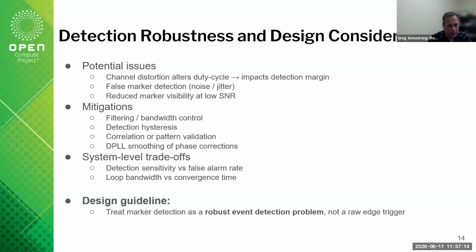So you can't have concepts like going backwards in time, which are going to be hugely devastating to something that's trying to capture events, and you have to worry about relative error time events of when those events occurred. Especially if the own system goes back in time and sends an event out that looks like it happened earlier than an event that happened within the same system just because you went backwards in time. You don't want that. So you want to be able to mitigate that cleanly through PLL smoothing techniques and do its own phase corrections, which means you won't go backwards in time.